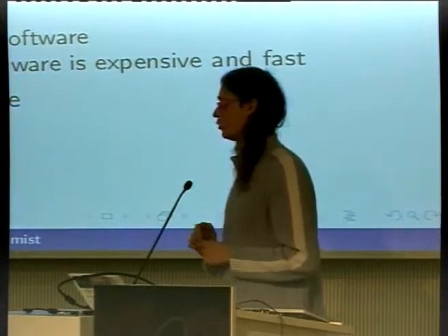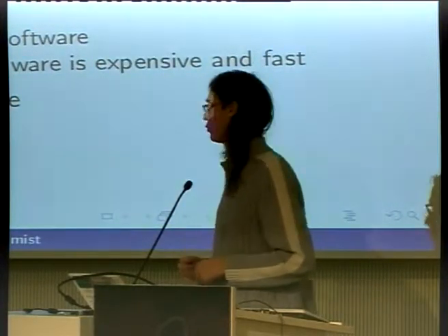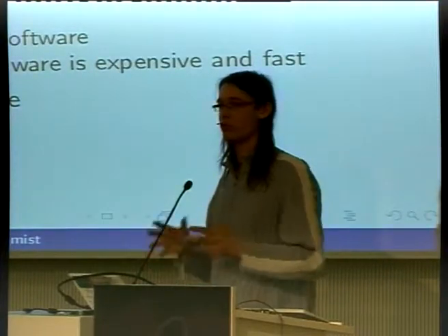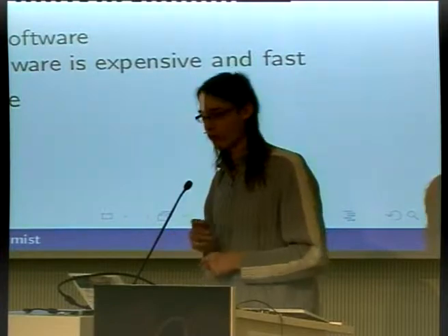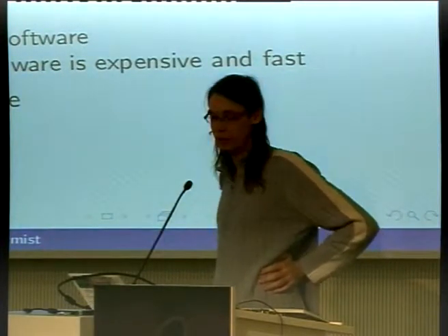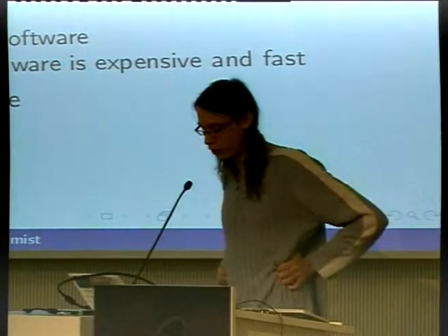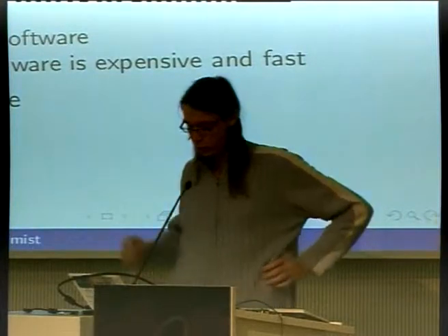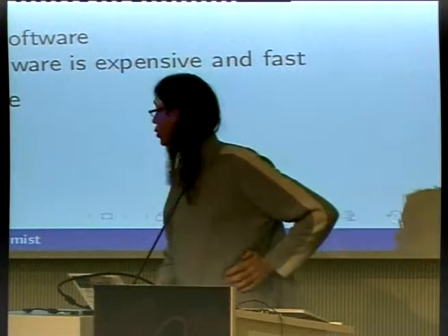A big problem that I had, which took me 1 year to solve, is the memory problem. Because you need a lot of memory bandwidth to take care of the video, and you also need a lot of memory to store the frame buffer, the textures, and everything. And the only technology which is capable of doing it is DRAM. And DRAM is very hard to take care of, especially at high bandwidth.